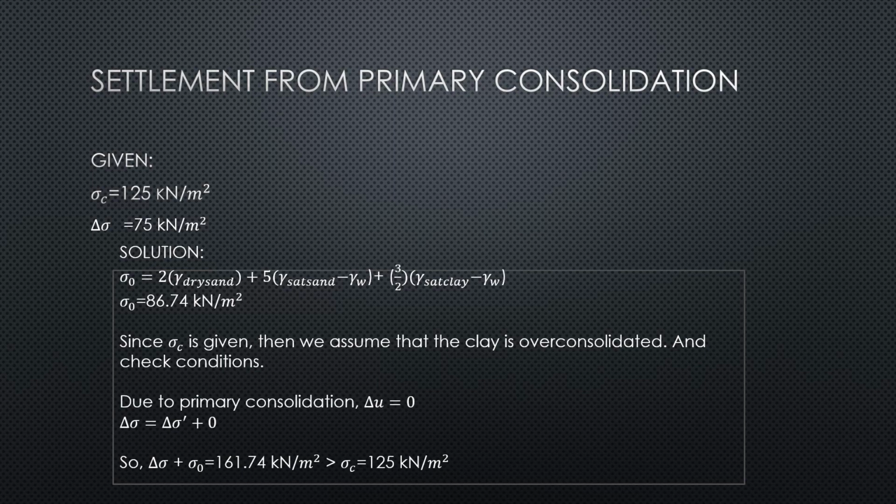I highlighted that earlier, that at the end of consolidation, primary consolidation, the water is fully expelled. So there is no water in the clay. So when there is no water, there is no pore water pressure. So the pore water pressure is equal to 0.